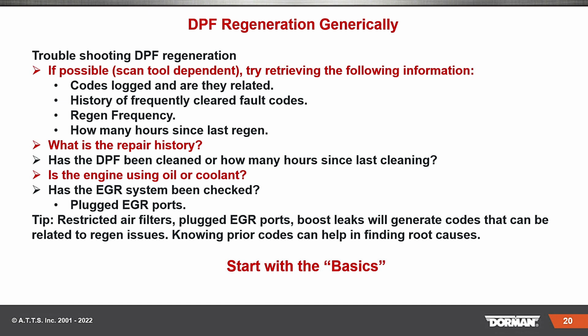Plugged EGR ports, a little bit of a tip here. Restricted air filters, plugged EGR ports, boost leaks, they're going to generate codes that can be related to regen issues. Knowing prior codes can help in finding the root causes. All day long, and I'm sure you guys have heard that over and over again: basics, guys. Go back to the basics.